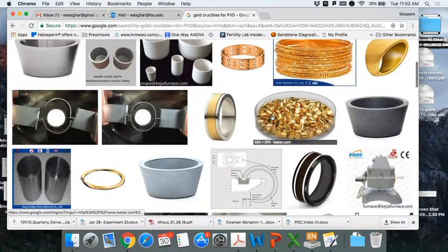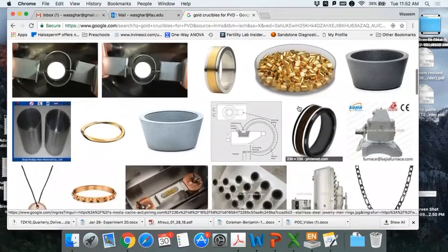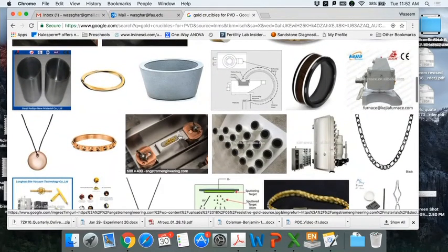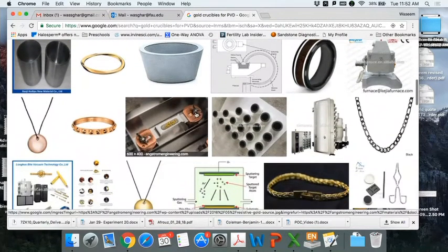Okay, for example, this is a gold pellet which can be used as a source. You can put it there in a boat, like this. So this is already loaded, right? Then you apply a very high voltage and current across these two terminals, and it will heat up this whole thing and start evaporating.